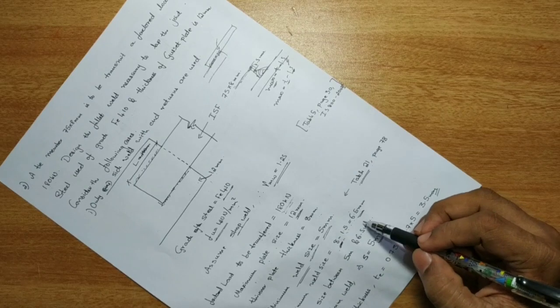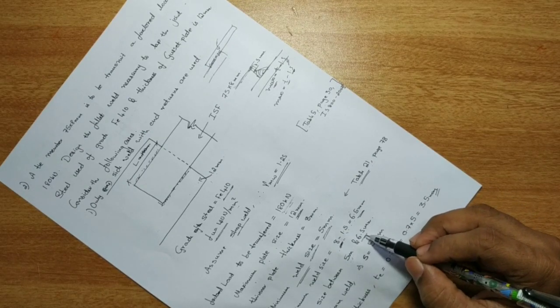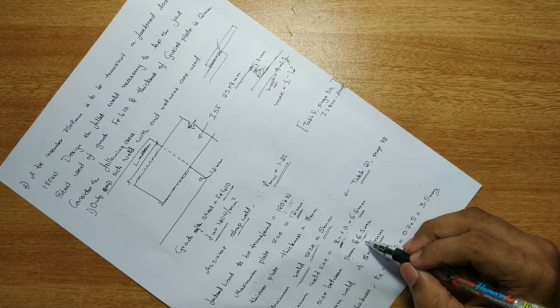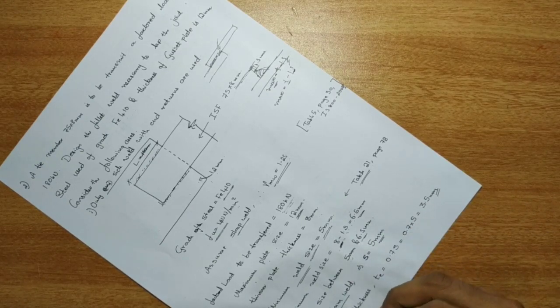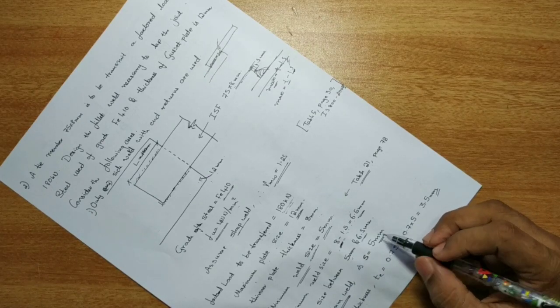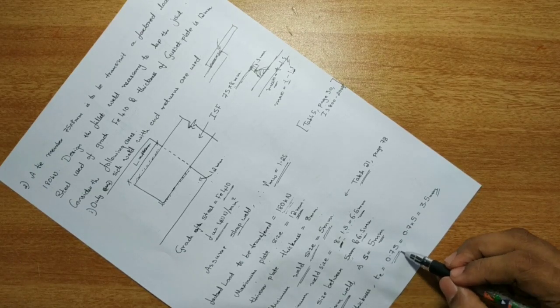So now you have the minimum limit and the maximum limit, 5 mm and 6.5 mm. You need to take between 5 mm and 6.5 mm. I'll be considering here to use a 5 mm weld, that is S is 5 mm. The limit will be 5 to 6.5. So the effective throat thickness becomes TE equal to 0.7 of T.